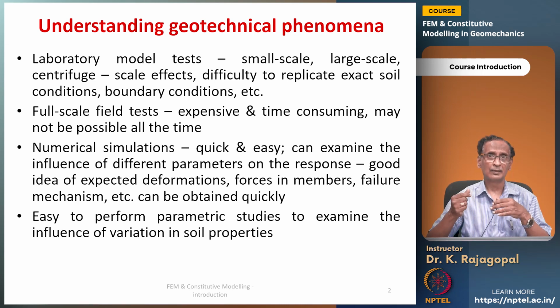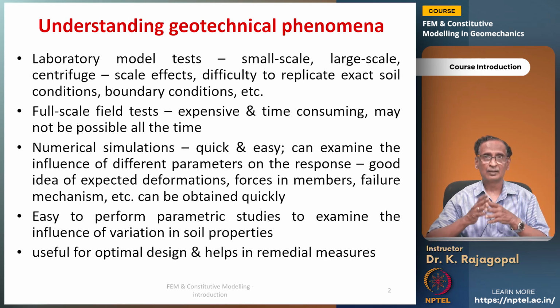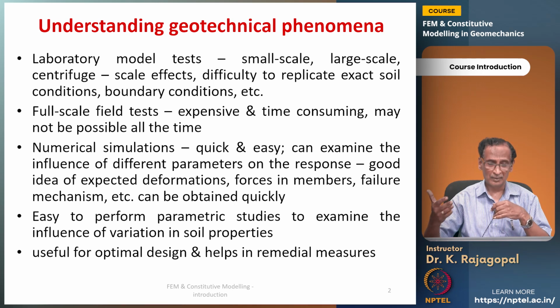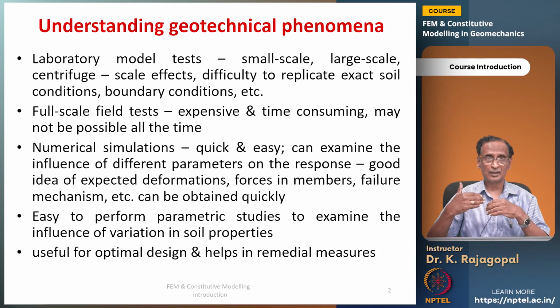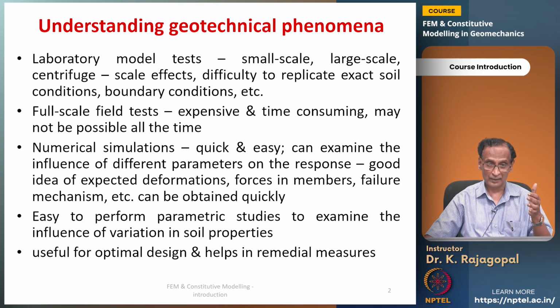And as I mentioned earlier, it is easy to perform the parametric studies to examine the influence of the variation in the soil properties. Okay. And these numerical techniques are quite useful in optimizing our design and also to take some remedial measures. Like let us say you come across some observation in the field, you can simulate that back in the numerical model and see what is the influence of different methods of ground treatment, and then use the best method for remediating your distress.